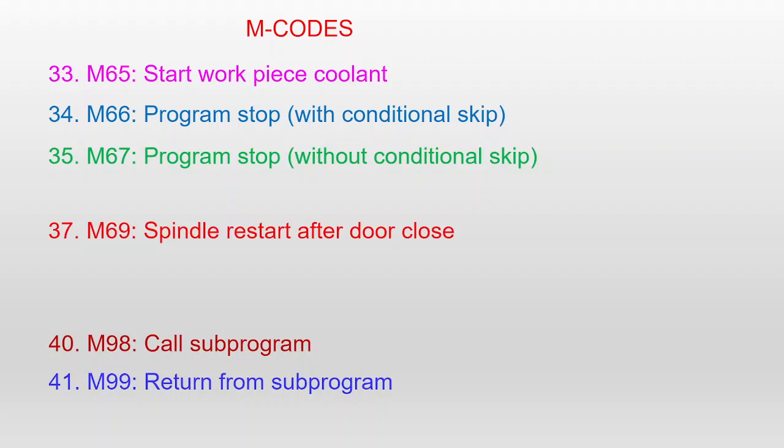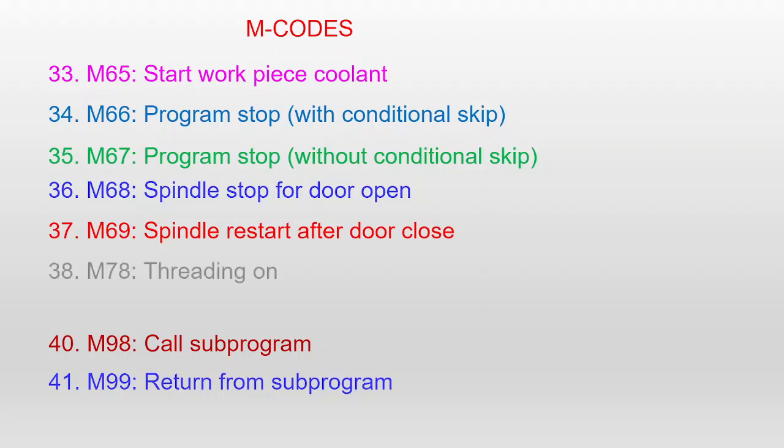M68, spindle stop for door open. M69, spindle restart after door close. M78, threading on. M79, threading off. M98, call subprogram. M99, return from subprogram.